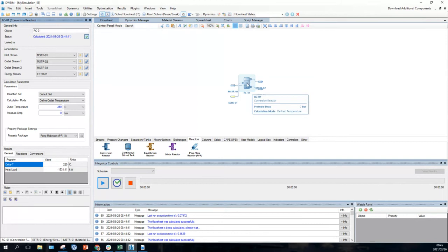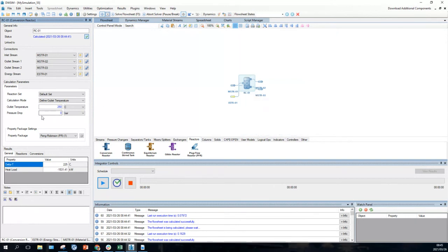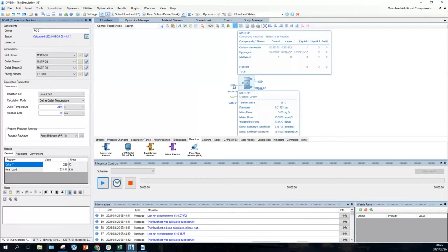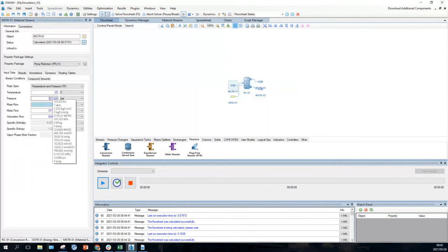Until the pressure changes, you don't want to. If you need to change the pressure of your system, and you've got a whole lot of succeeding unit operations, you only want to change the pressure at one place. So if you choose all of them to be a pressure drop of 0 bar, or whatever small pressure drop you'd like to put in there, if you're using pressure drop instead of absolute pressure, you only have to change the pressure at one point. So I'm going to change the pressure over here, and that's going to be 20 bar pressure.